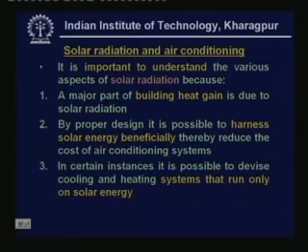And the third reason is that in certain instances it is possible to devise cooling and heating systems that run only on solar energy. This is very important as far as energy conservation is concerned, because in some cases, for example using an absorption refrigeration system, you can devise an air conditioning system which runs only on solar energy. So it does not require any other energy input.